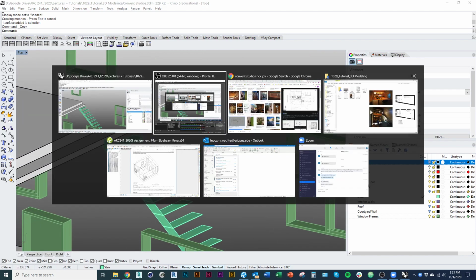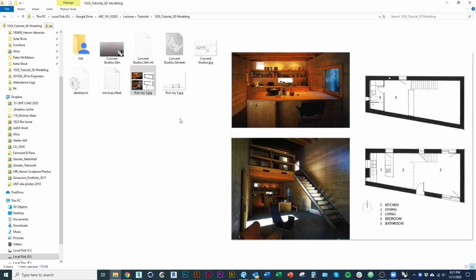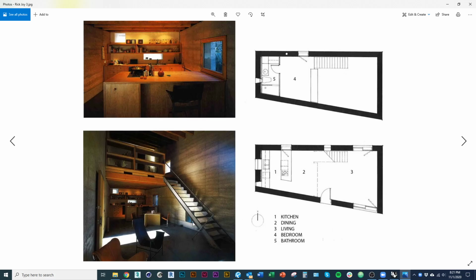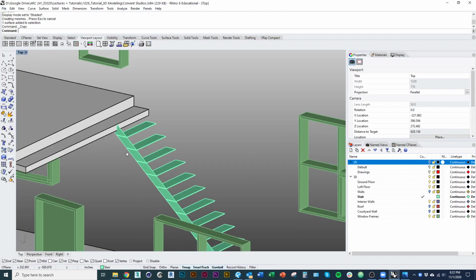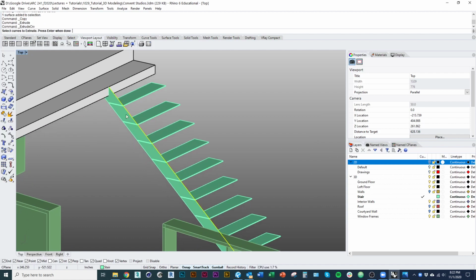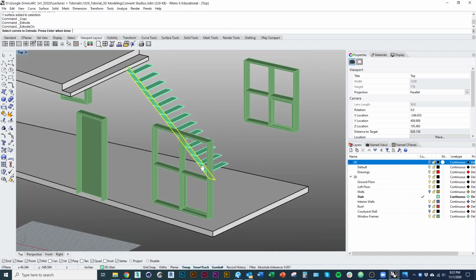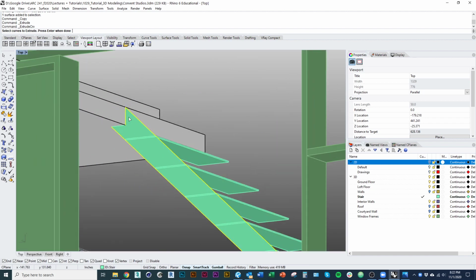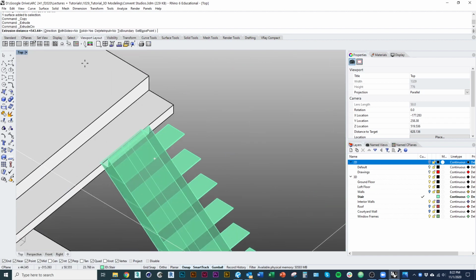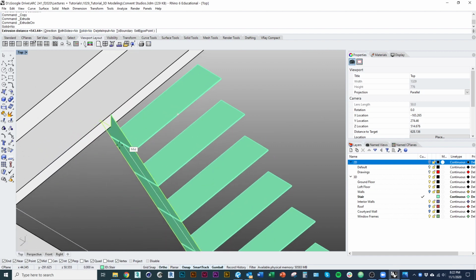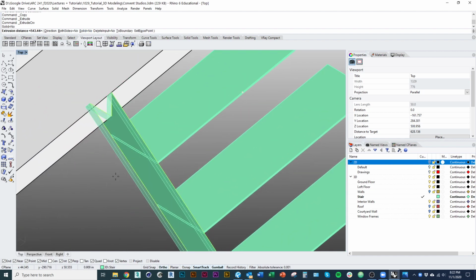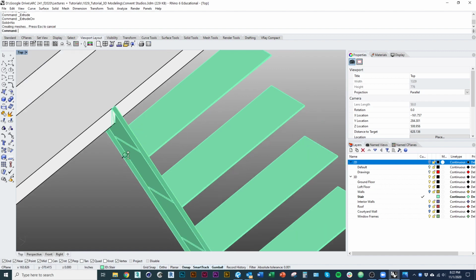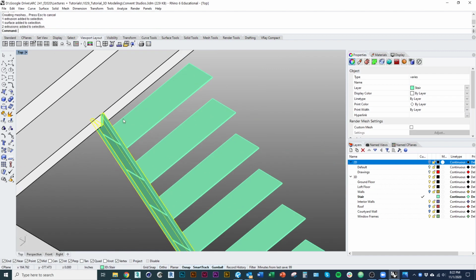And if you look at the actual building here, you can see it's got kind of a depth. It's like a flange, you know? So we're going to extrude out the edges so that we have that same thing on ours. So I'm just typing in extrude curve, and I'm selecting the outside edges. And this time I'm turning solid to off. That shouldn't be solid, and I'm giving it a little bit of depth. Show that it's a beam like that.